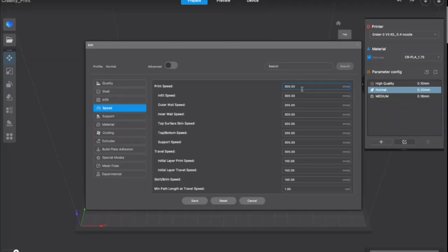If we print a part with high speeds, the nozzle will move very fast, and that won't have precise coordinate dimensions. As it is moving very fast, it will have some deviation from the actual dimensions. So if we want a precise print, you need to print at low speeds. But if you want the print to be done in a quicker way, you can print at a high speed.